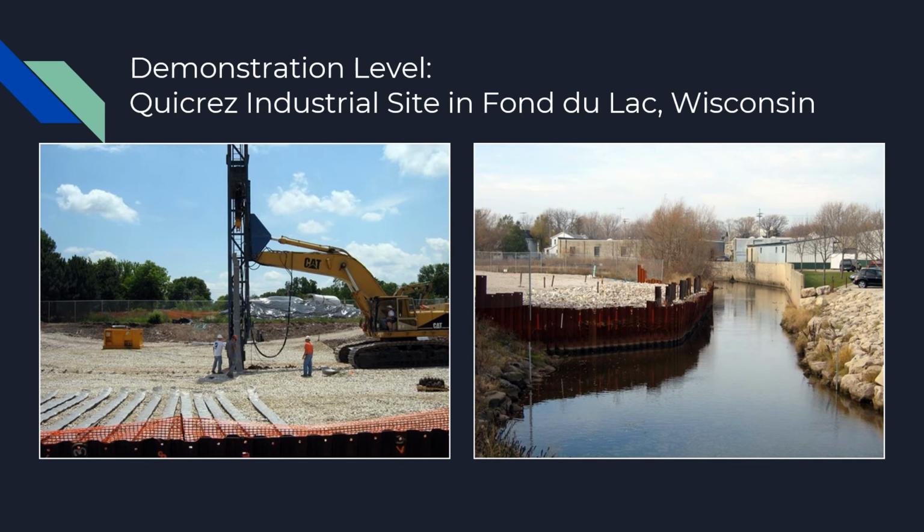The system was exposed to 208 volts initially. The initial DC output measured somewhere around 190 and 500 A. Once the site started heating up to the operating temperatures of around 50 degrees Celsius, the power was reduced to 110 volts and 450 A. Monitoring of this site was done remotely, thereby saving some operational costs. The entire project lasted over 2 years until 2008.